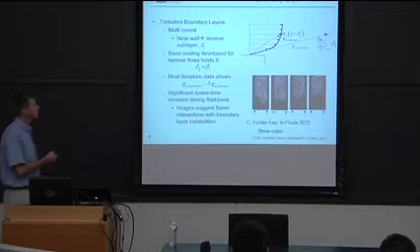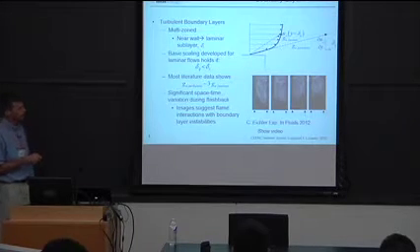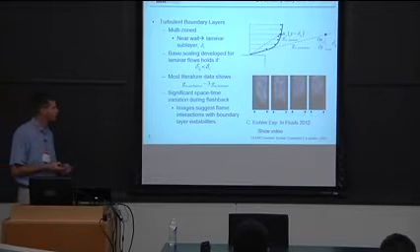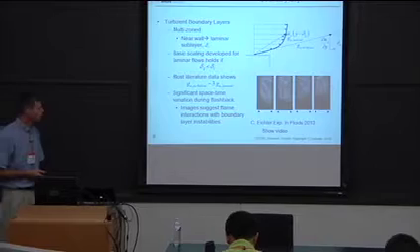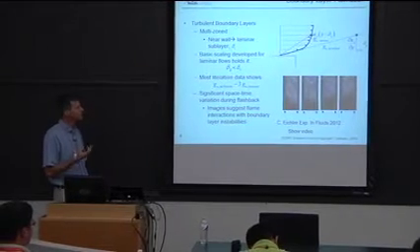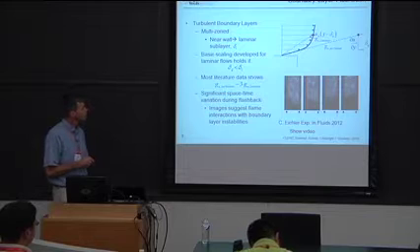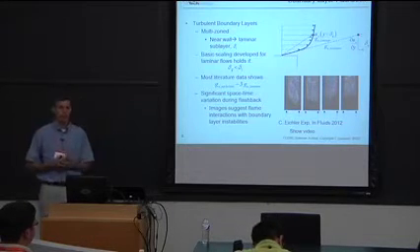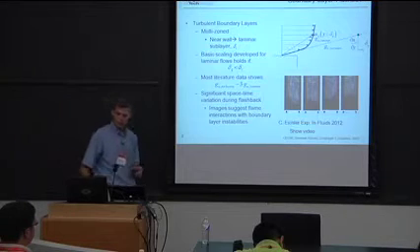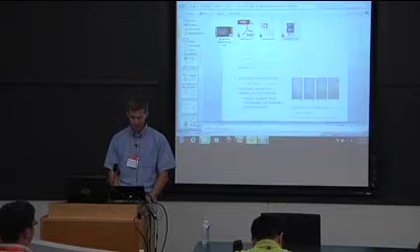And so it turns out that most literature data shows that the critical velocity gradient in turbulent flows is about 3 times the laminar value, which tells you that this inequality doesn't hold. But still, same basic idea, it's just that you can't use that simple first-order Taylor series expansion to approximate what's happening. What's also interesting in turbulent flows is, as I mentioned, there's significant space-time variability.